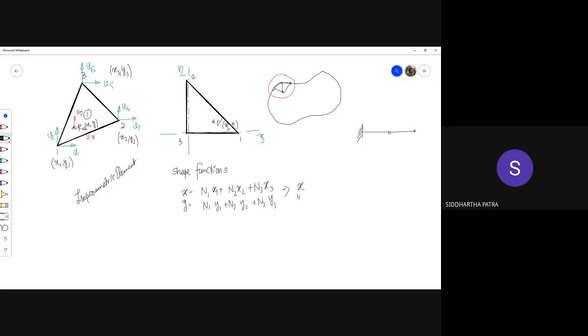Now this time x is represented as a vector, which basically means it's a coordinate vector, and this is how it must be written. For any interior point of the element, its coordinates are basically this N matrix times x hat. This is a 2 cross 1 vector, so this needs to be a 2 cross 6 matrix.